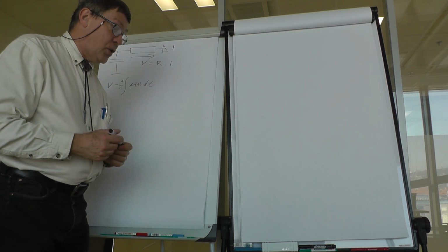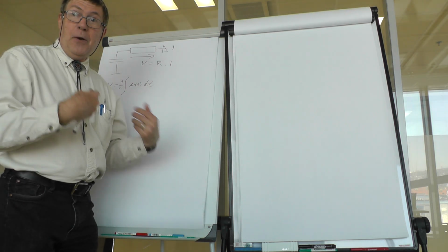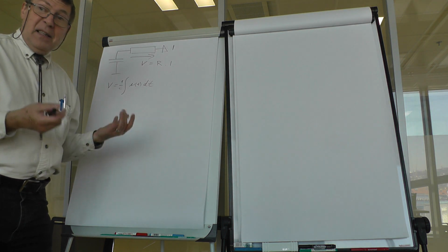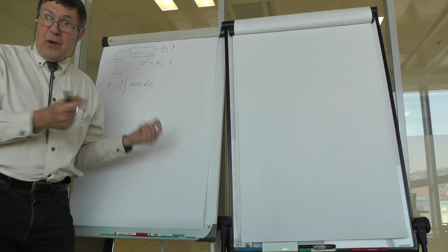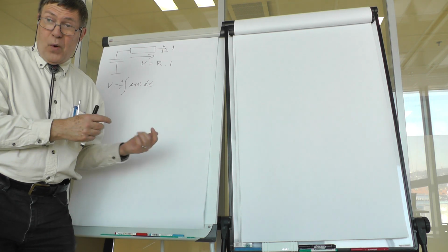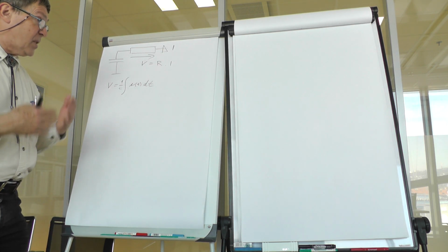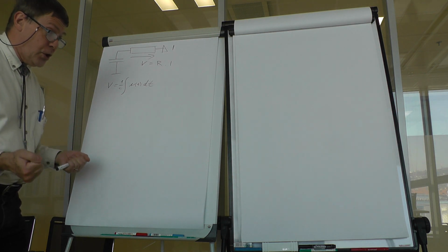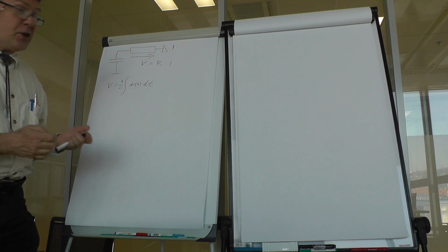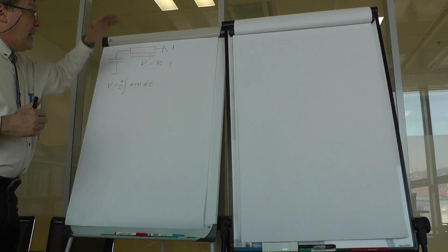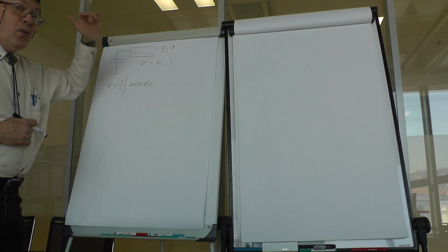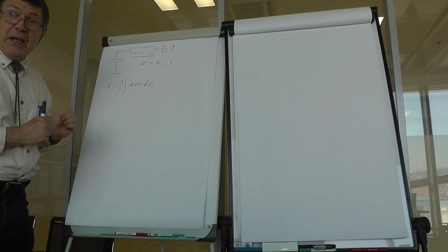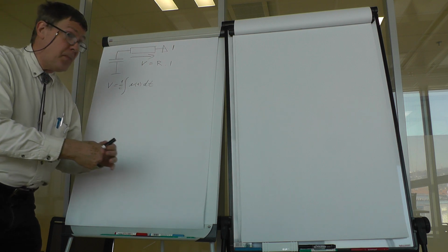Within SPICE we choose converting everything to differential equations, and then we would apply time stepping solution of those differential equations. We have addressed that a little bit earlier, so we have already been talking about a way of solution of multiple differential equations. So this is verified. We have an electric circuit. We in any case can express it with a set of differential equations and then solve that.